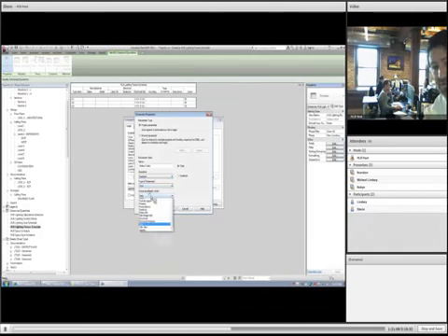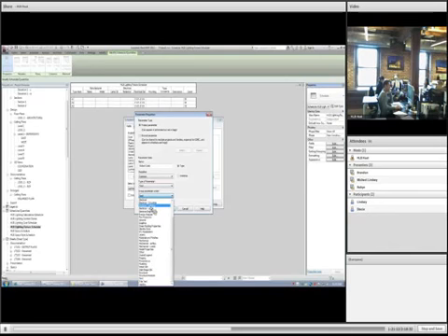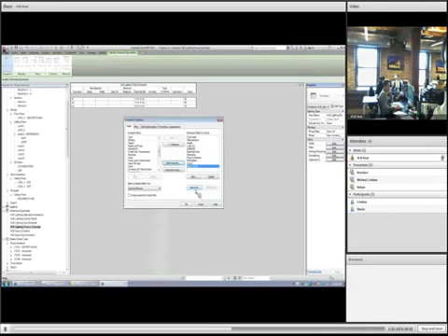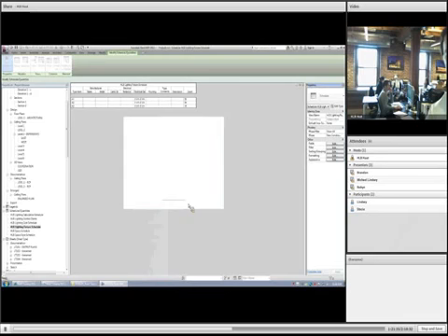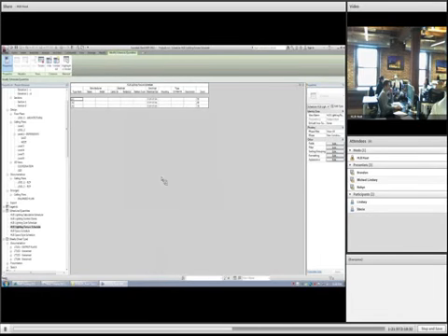We're just going to make this a text parameter. We're going to group the parameter. We can still group it under as being an electrical item, right? Because it's ballasting. Ballasting codes. I'm going to check electrical lighting. We'll hit OK. Okay, so it defaulted to being on the bottom here. We're going to move it up to, I guess, put it under ballasts. Ballast code. Hit OK.